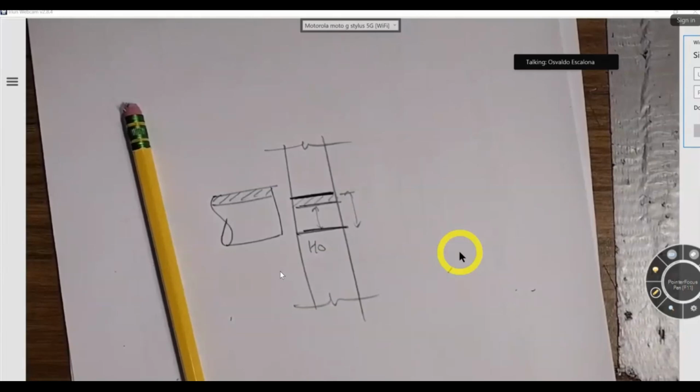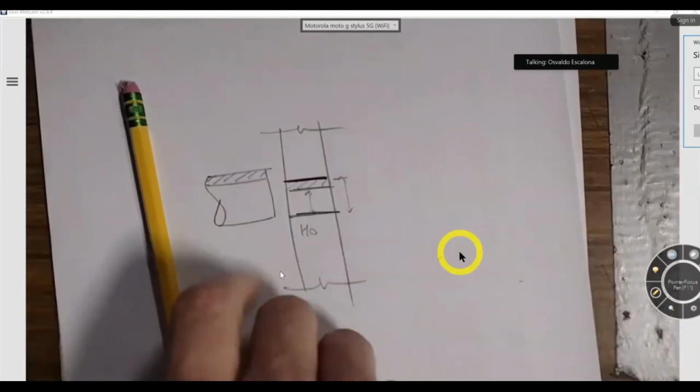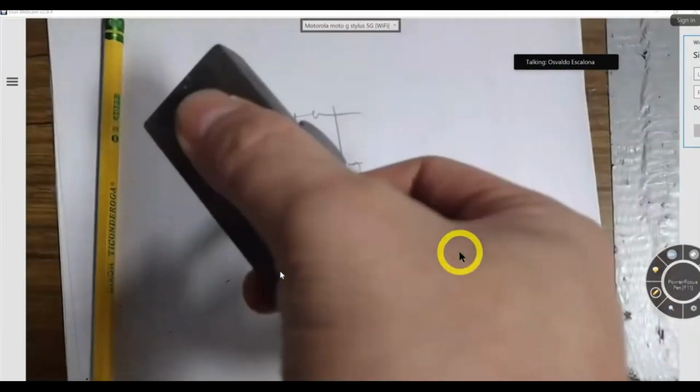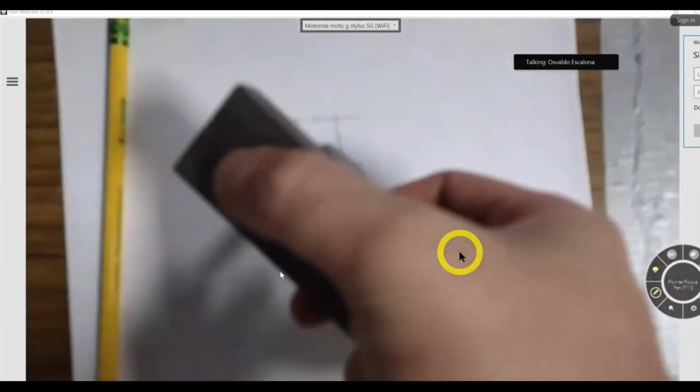No, right? So what do I do to that hole? I heat it up, with that thermal expansion. It grows a little bit, right? And then I grab that pin and hammer it in. That thing will never go anywhere. In fact, you can try it. The only way I can take this one out is most likely to destroy it.